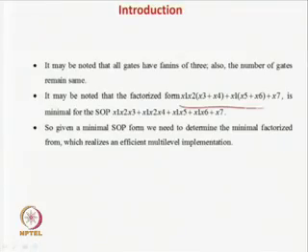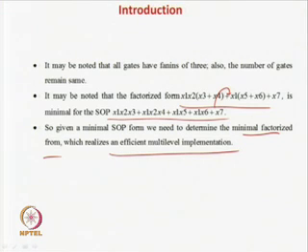So, this is actually the best way of factorized term for this one. So, this is the minimal representation, because no more terms can be factorized anymore. So, this is the minimal factorized form which is realized as a multi-level implementation. So, that is the target. So, we will be giving a sum of product form in this way, and you have to go for a maximum factorized form. That is what is the minimization in multi-level implementation.